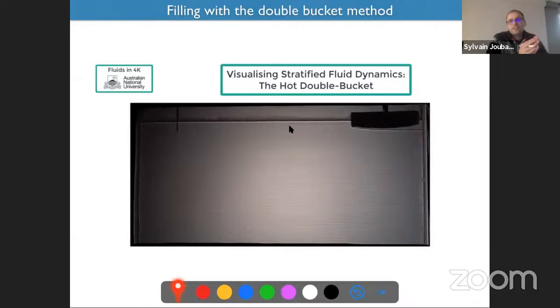And of course, experimentally, we don't want to fill a tank in many days. So we want to fill the tank in a few hours. So you choose the flow rate Q2 that is large enough to have a filling that is not too long, but not too large, so as not to have mixing. So it's just the first try when you have a new setup that will tell you what is the good flow rate you need to use to have a nice stratification.